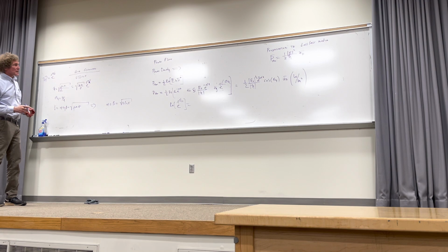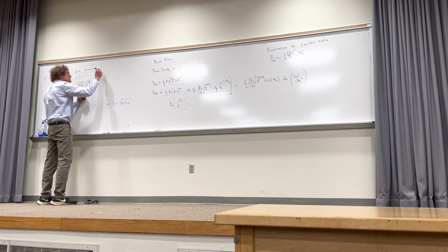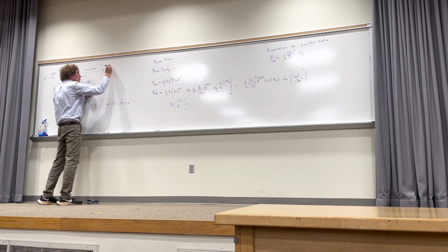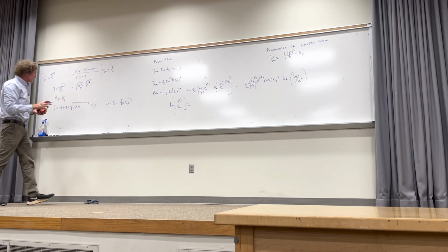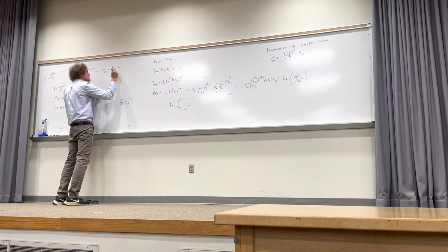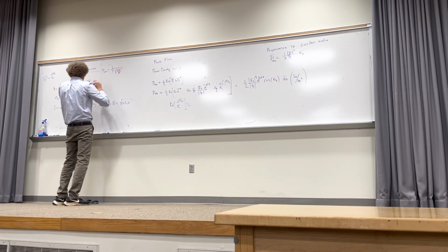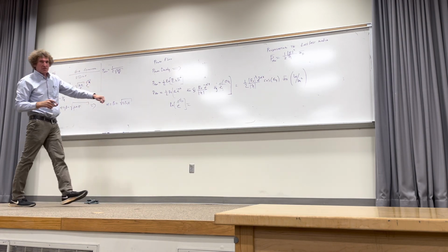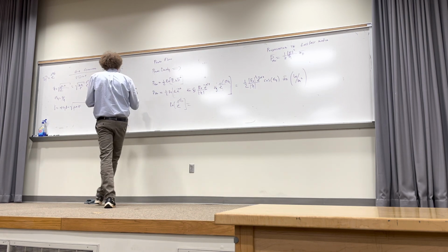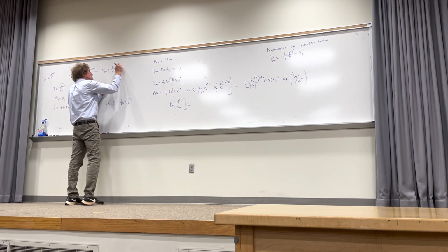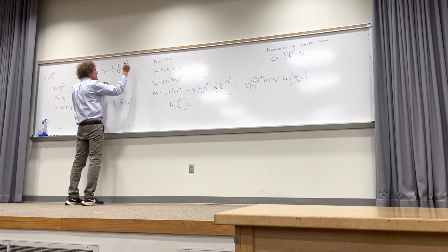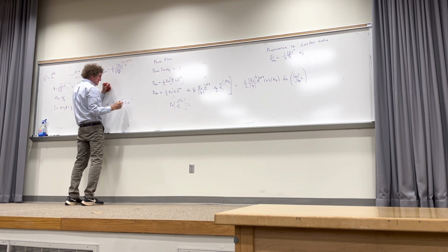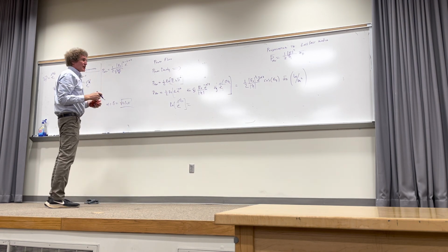Now I come over and I'm going to get the power flow in a good conductor, and I'll do it right here. So it's 1/2 the magnitude of eta. Well, the magnitude of eta is just the square root of omega mu over sigma. Then it's going to be times E naught squared, whatever E is, times e to the minus 2 alpha z. I'm just going to leave it as alpha, because it's given as this. Then it's going to be times cosine of the angle.